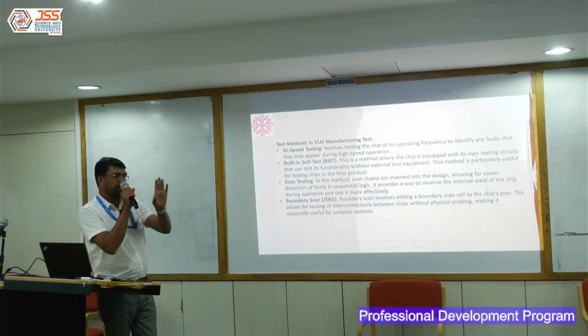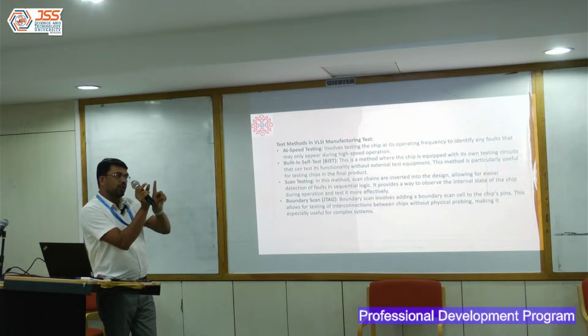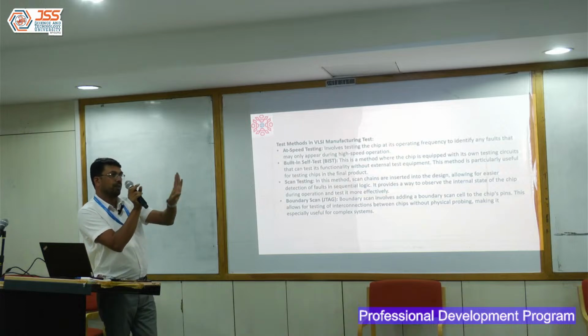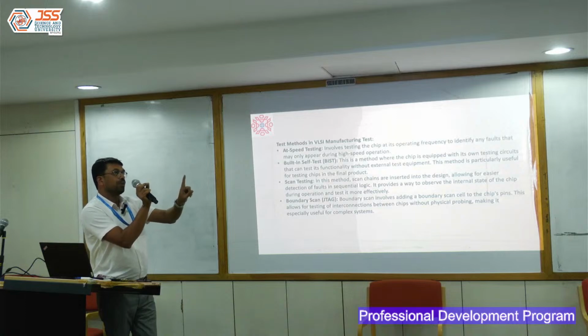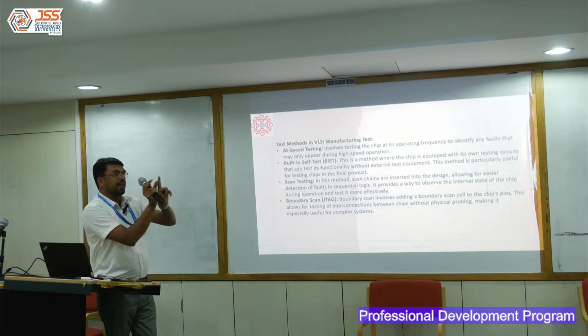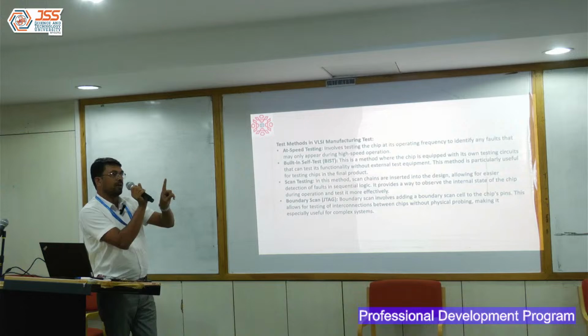If I'm increasing or decreasing frequency, I'm just moving the clock edge. In the timing domain, it's nothing but the clock pulse width. I'm just moving that edge, but your hold definition also moves with that edge. If the clock edge appears here, the minimum amount of time is say 8 ns, during which the data has to be stable.